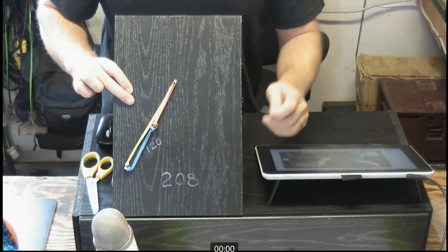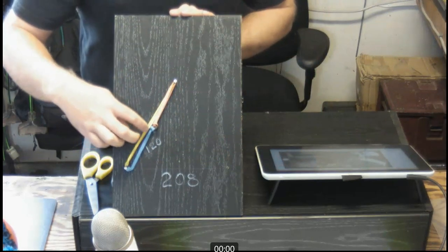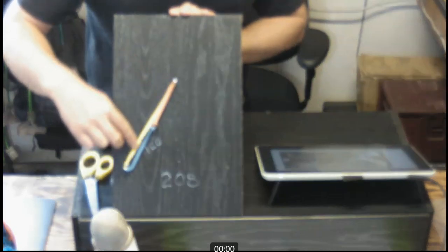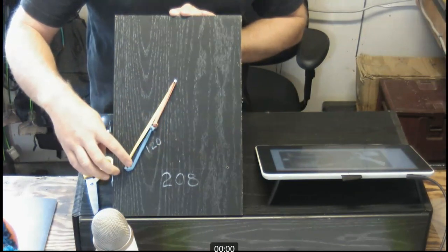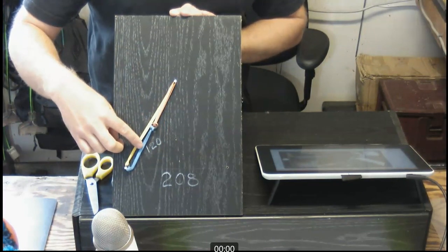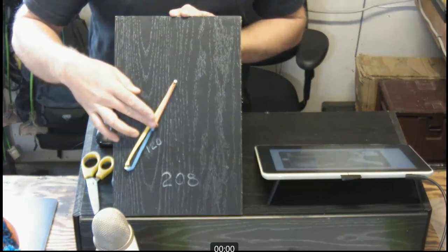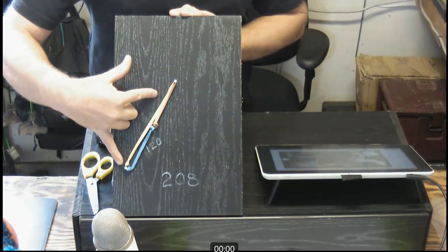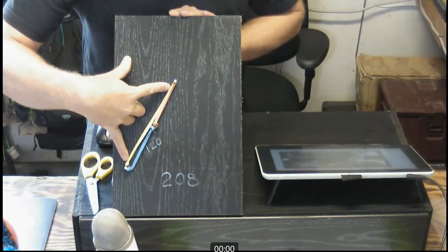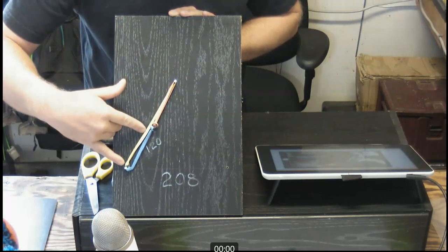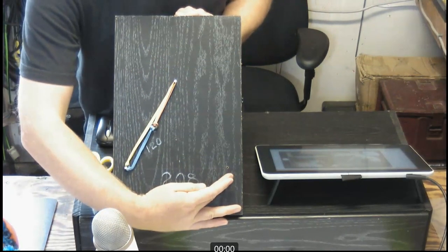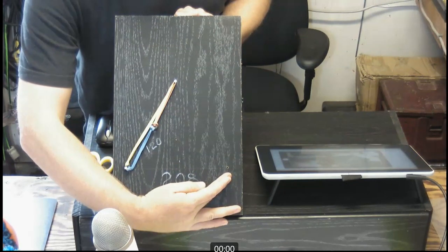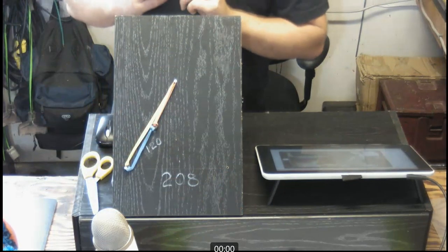When we do that, what we see happen is that this phase over here is going to be unaffected, the one that's represented with the yellow. These other two phases are going to snap directly across from point to point, but they're each only going to see half of whatever I had for my voltage. Because we know that from here to here was a value of 208 volts, therefore, half of this is going to be 104, half of this is going to be 104. And it's just because we've lost this line, which before was stretching it out and across to there, that we now have this sort of an issue.